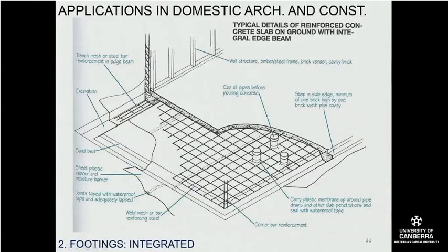Now when you're doing this, you must remember to have all your pipes ready in place, because once you pour the concrete, it's a real pain to move the pipes around. So you better be sure that it's not going to cause you grief later. Make trouble for you later.